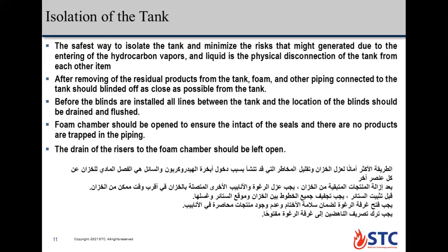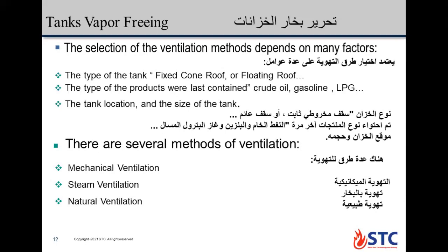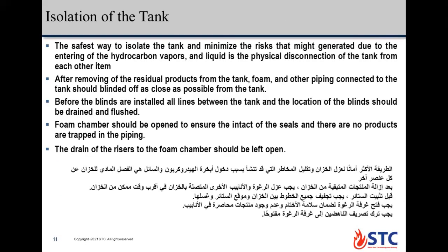Isolation of the tank. Okay, no problem about this. Maybe again. The safest way to isolate the tank and minimize the risk that may be generated due to the entering of the hydrocarbon vapor and liquid is physical disconnection of the tank from each other item.